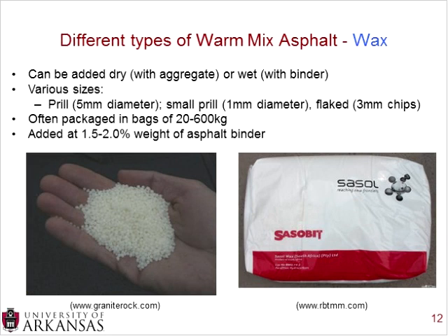Moving on to the wax technologies of warm mix asphalt. Wax additives can either be added dry, which is where you would traditionally treat them as another aggregate, or you can add them wet, which is where you mix them with the binder. And there are considerations both ways, especially if you have a plant. Do you have extra space for a stockpile that's covered, or do you want to add the wax into a binder that will take up an exclusive tank? Those are things that need to be thought about.